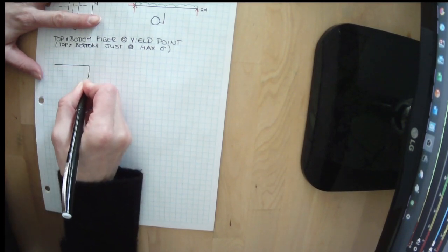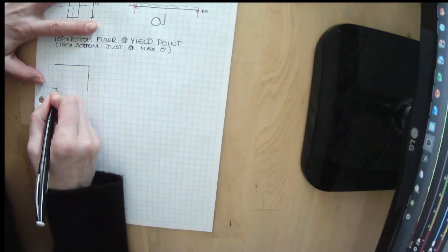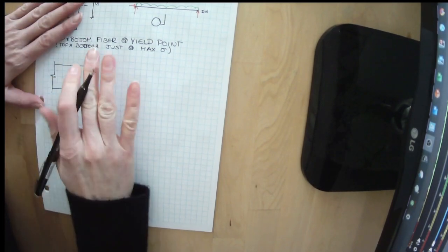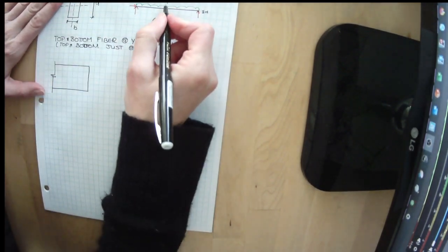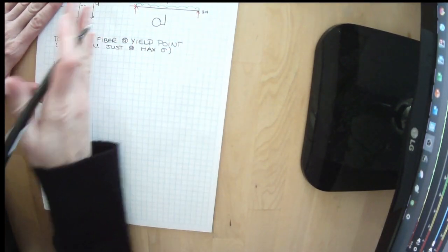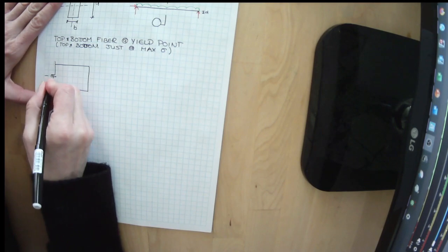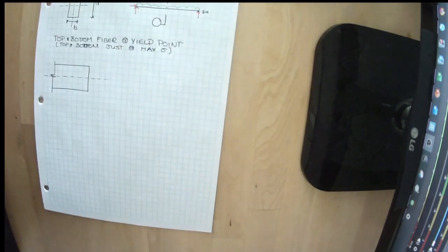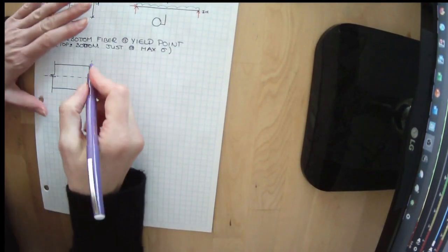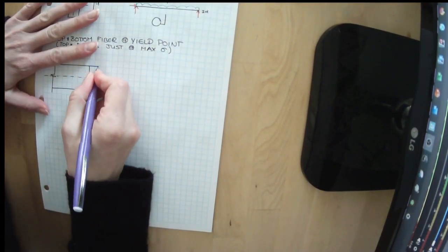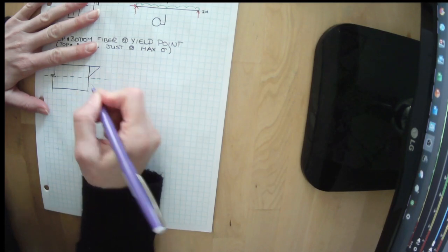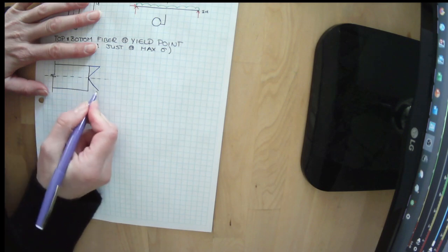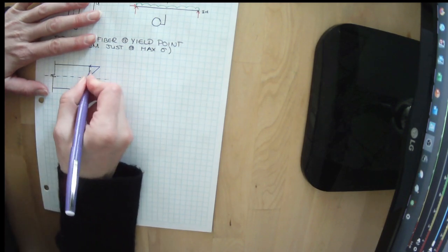So we are going to take a cut of that beam that we were just looking at. And we know it continues here, and we know it continues here, but we're cutting along a plane. So we've cut along this plane here, and there's the neutral axis. And we know that the internal stresses hit their maximum at the top and bottom fibers. So here and here.